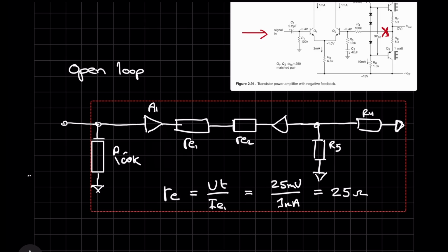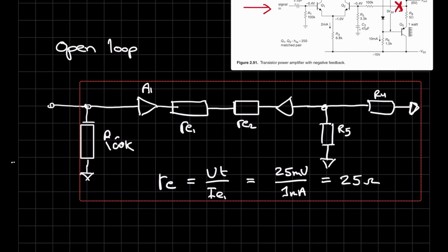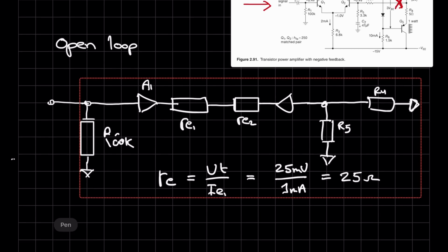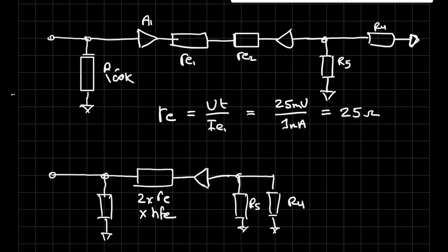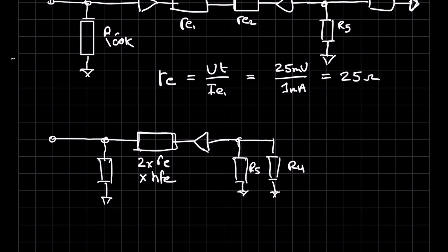You can see this gain over here is going to effectively amplify the resistance that's here for the input signal. So we can redraw that again, similar to this. We've got rid of our gain on this side, and we have our RE resistors for both Q1 and Q2 represented with this single block. Now the resistance on this side is going to be divided by this gain, because it's acting in the opposite direction. So this is going to be two resistors in parallel.